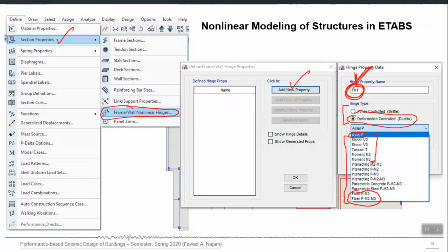By doing so, you will be telling the program that the axial force in that beam or column versus the axial shortening or elongation in that beam or column should follow this behavior which I give, right? It should not follow P is equal to delta over AE, that elastic formula. It should follow my behavior, right?